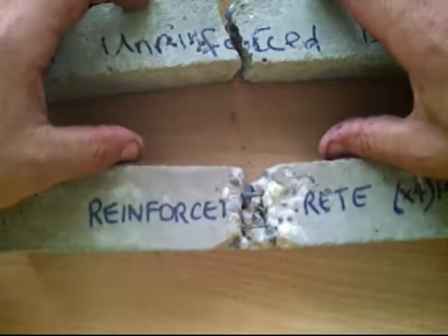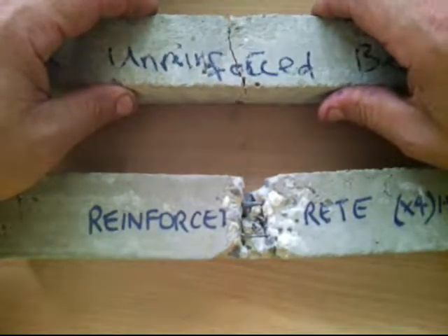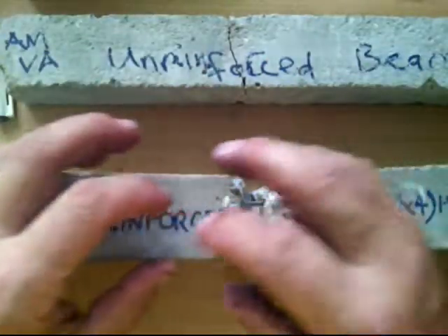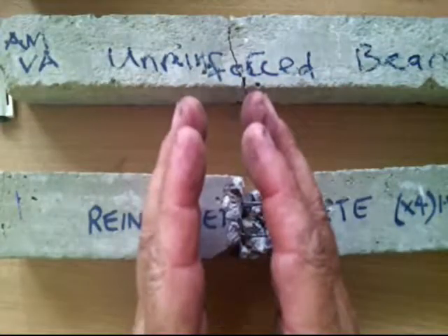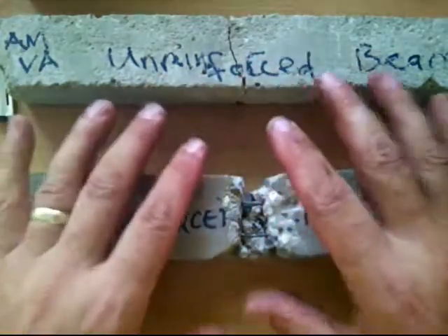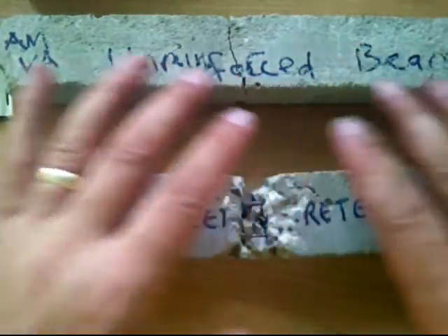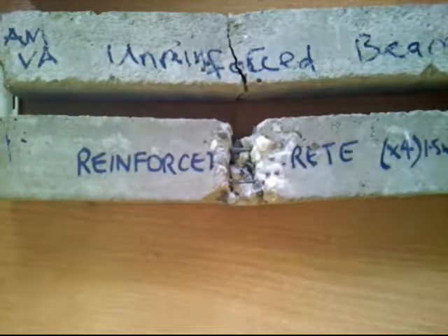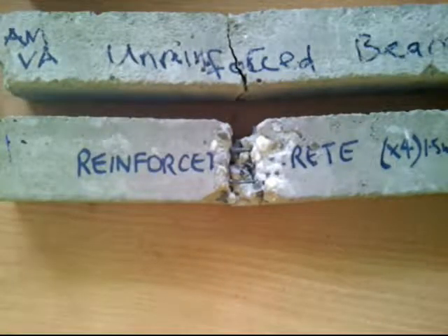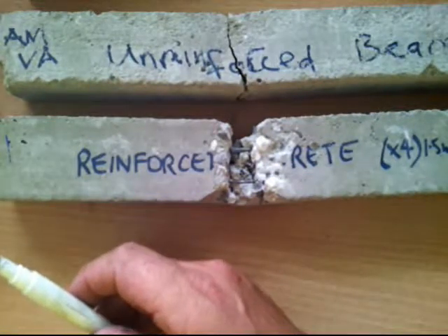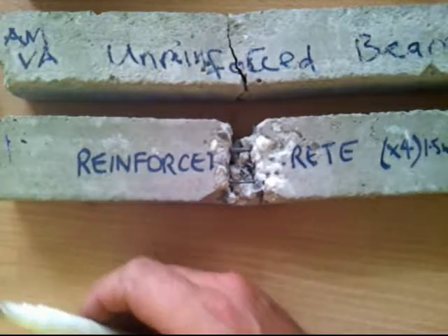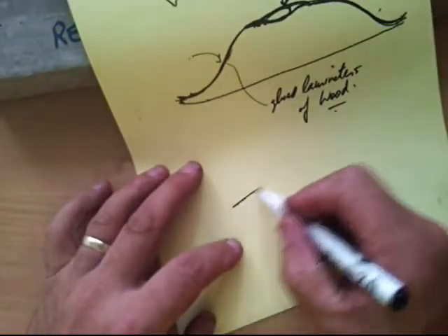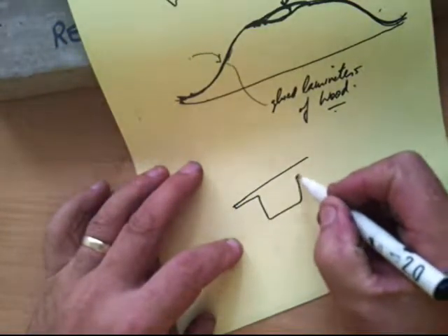The other way is post-stressing, and post-stressing means that we're going to create a beam, and sometimes this is done in pre-stressing and post-stressing, but often if you have lots of large sections that you need to put together, for example a roadway of an aerial bridge, or a bridge that's suspended, or a car roadway that's suspended, a lot of the sections will be made in shapes that are precast off-site, and those shapes, I'll draw a picture for you,